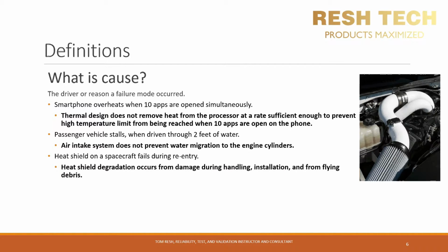In the case of the passenger vehicle that stalls in 2 feet of water, it is time to take a look at that air intake to make sure that the location of the inlet to the filter box is not in a location that can easily pull in water, or you may need to add water or moisture resistance such as baffling or traps to prevent water from making its way into the engine.